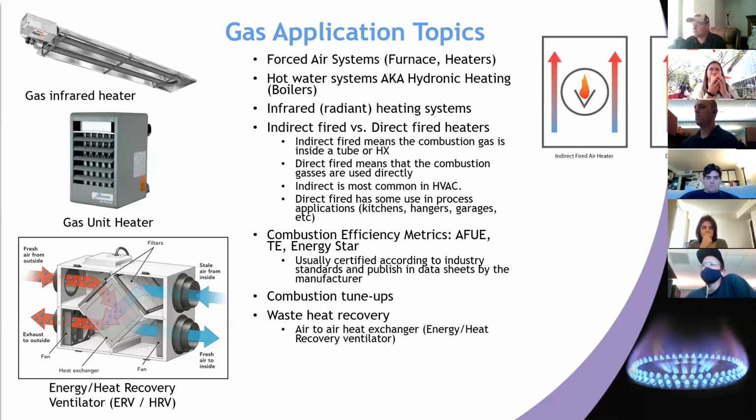If you don't have enough oxygen in the combustion chamber, you're going to produce carbon monoxide, and that is both a health and safety hazard. That's a very poisonous gas, and people can and have died from carbon monoxide poisoning. You probably have a meter in your house for it. It's also an incomplete burn, and so you're wasting energy because there's still combustion energy that could be extracted from that carbon to oxygen bond. So a well-tuned piece of equipment can get away with about 3% excess oxygen coming out.